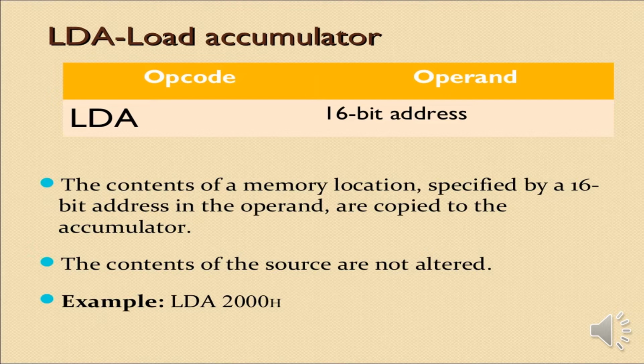So LDA is an instruction that copies the content of the memory location whose address is given within the instruction into the accumulator. The content of the memory location remains unchanged. In this way we can copy the memory location data into the accumulator.